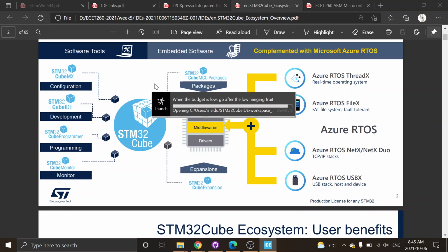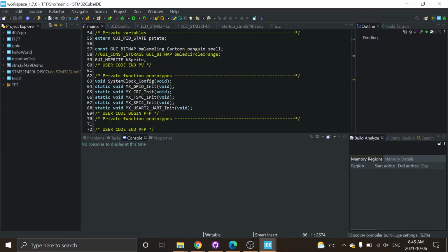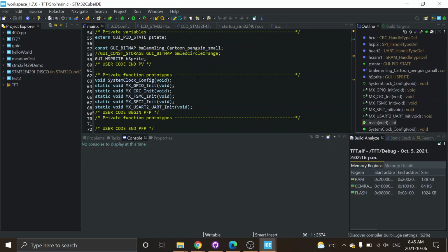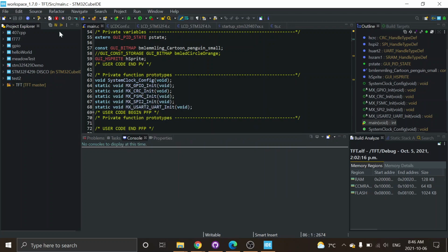You could use TensorFlow in Google Colab and generate a model to sense vibration, what's normal for a motor, and then if something's starting to go, like a bearing, have it trigger that you detect an anomaly. You can develop that model on a PC in Google Colab, for instance, and then shrink it down, and they have a package that will let you put it onto an embedded device.